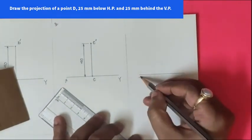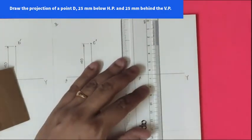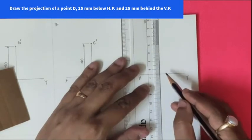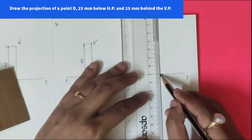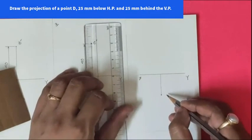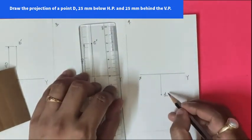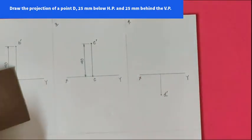This is your XY line and your front view will be at a distance of 25 mm below the XY line. So this is our front view. This is your d dash. Front view, so always use dash. Top view, do not use dash.